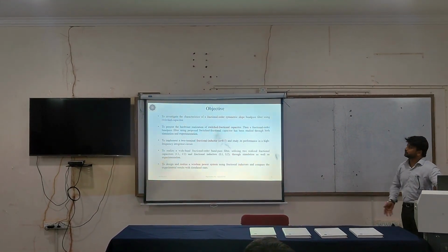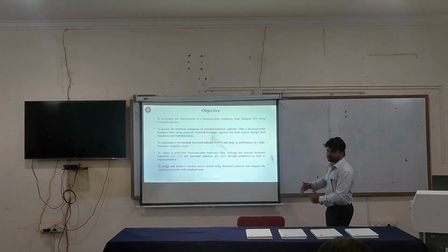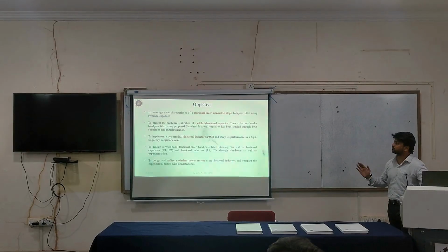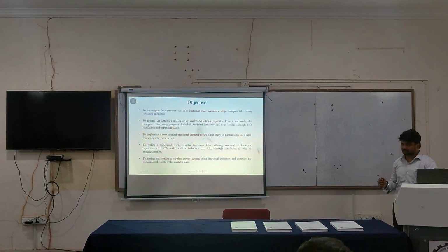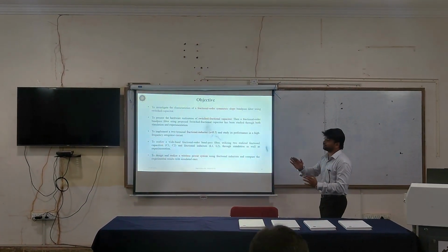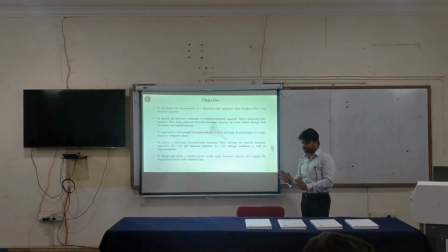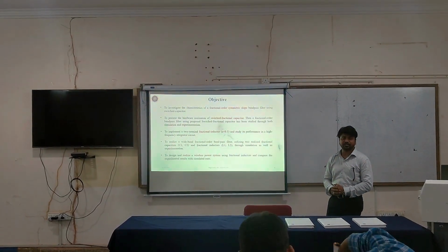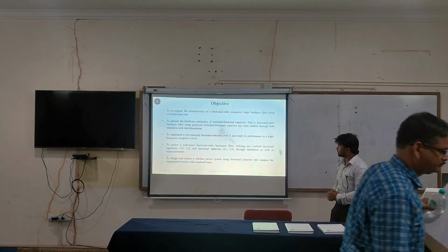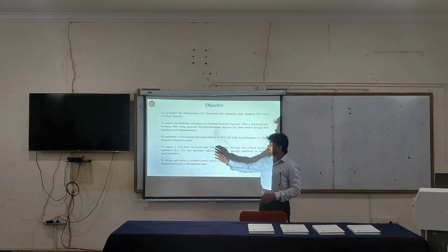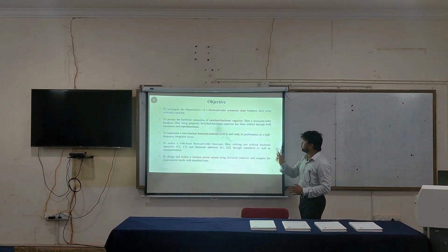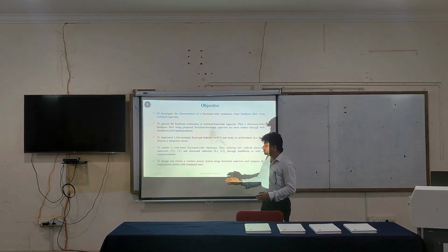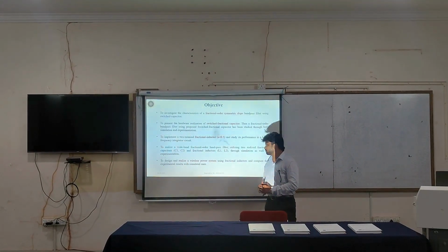Now, coming to my objective. These objectives reflect each and every chapter of my thesis. First is to investigate the characteristics of a fractional order symmetric slope bandpass filter using switched capacitor; to present the hardware realization of a switched fractional capacitor, then a fractional order bandpass filter using the switched fractional capacitor; to implement for the first time a two-terminal fractional inductor of order less than 0.5 and study its performance; to realize a wideband fractional order bandpass filter using the two realized fractional capacitors and this fractional inductor. Again, to use these fractional inductors to realize a wireless power transfer system.